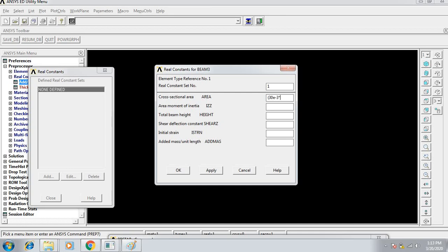I'm converting that into meters, so 40e-3 meter, mm will be converted to meters. The area will be converted from mm square to meter square. Meanwhile b, the base, is 30e-3 multiplied by 40e-3, because I am converting that to meters, cubed, divided by 12, and convert the height also in meters, 40e-3. Whichever values you don't know, please do not enter any values.